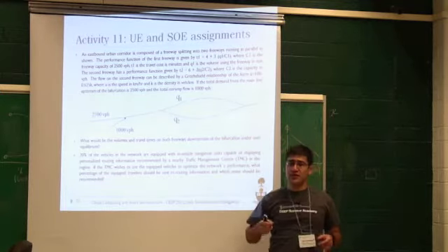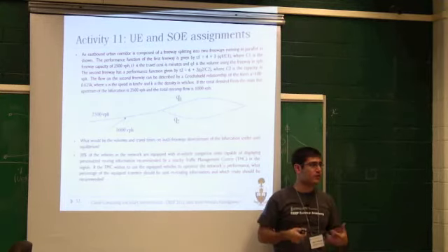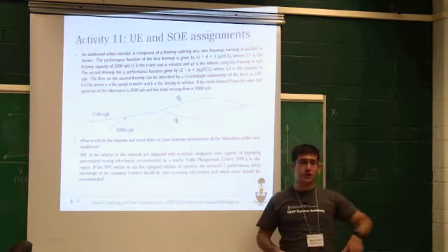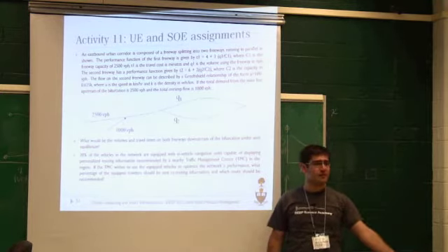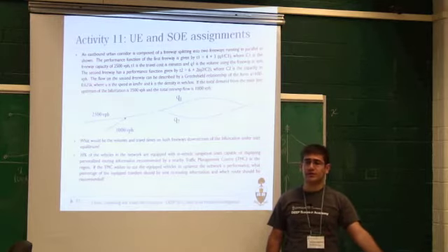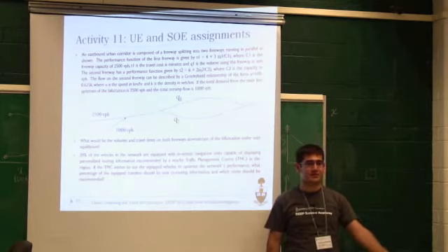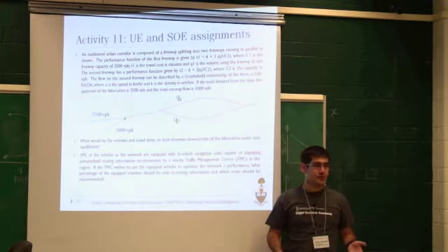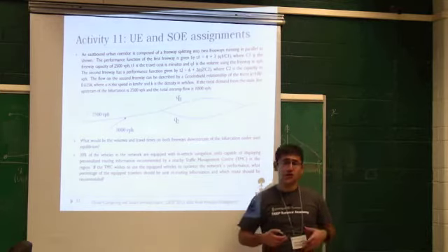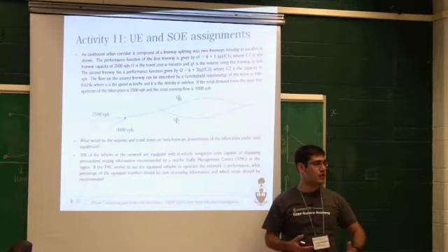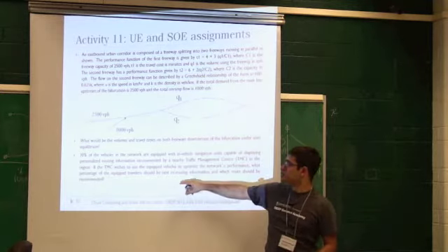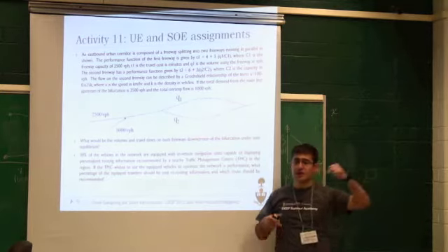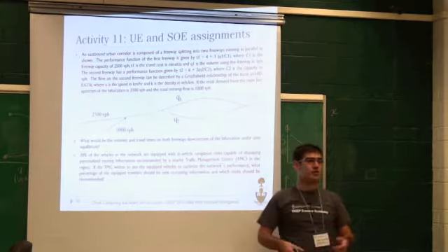As a traffic management center, you're supposed to come up with a system optimal solution, and then try to see how people originally behave. Based on what? We just did it. If I don't give anyone any information, what would they do? User equilibrium, right? So after you come up with your results, you should see how people originally behave, and then use the 20% here to shift the behavior from user equilibrium into system optimal, as much as you can.